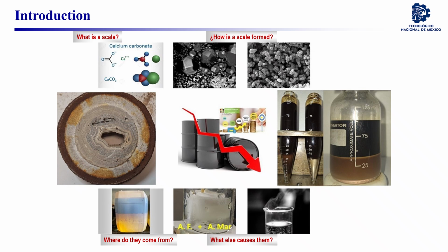Production consists of hydrocarbons, formation brines, and emulsions. Emulsions are precursors to mixed scale. This is defined as a scaling solid composed of inorganic salt combined with a mixture of asphaltenes and resins.